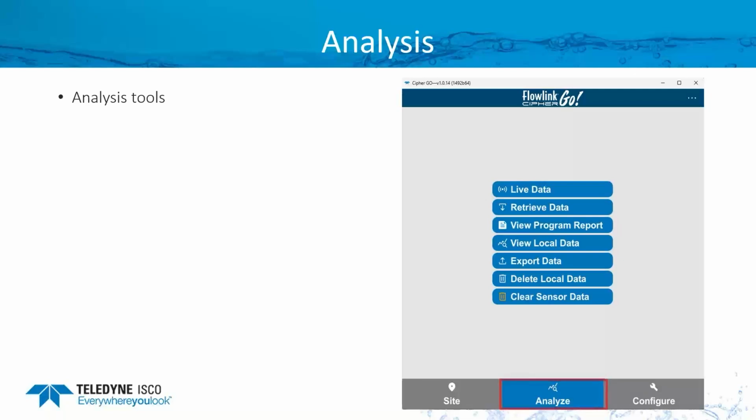You know, what's your data storage going to be? What is your flow rate set up for? What kind of primary device? What kind of units of measure? All that, as far as setting up the modem and how often it's going to push, that is your configure. The analysis is really, once you're on site, possibly you just deployed it and you want to make sure everything's working well, or on return visits,